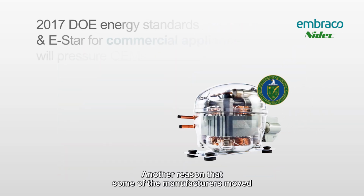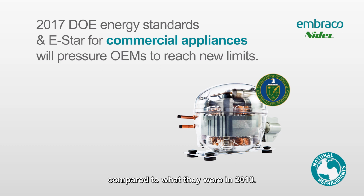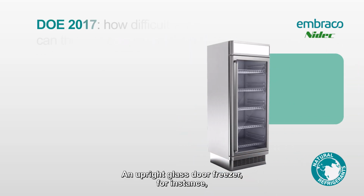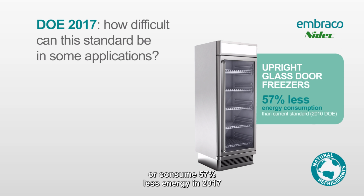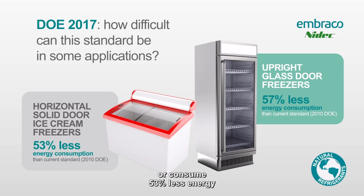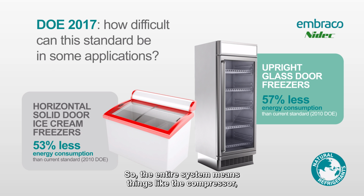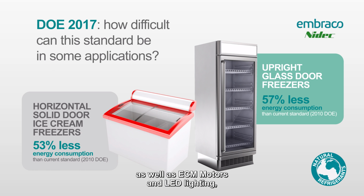Another reason that some of the manufacturers moved towards flammable refrigerants is in 2017, the DOE energy standards came out, and they had very high new limits compared to what they were in 2010. An upright glass door freezer, for instance, needed to be 57% more efficient or consume 57% less energy in 2017 to meet those standards than it did in 2010. And for a horizontal solid door ice cream freezer, we had to be 53% more efficient or consume 53% less energy than we did in 2010. But now they needed to look at the entire system. So the entire system means things like the compressor, but also things like the refrigerant, as well as ECM motors and LED lighting and anything else that they could do to squeeze more efficiency out of these systems.